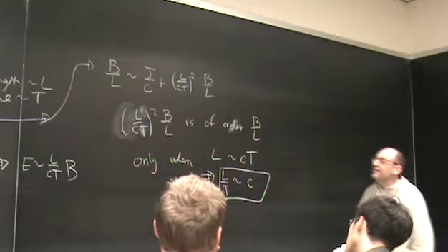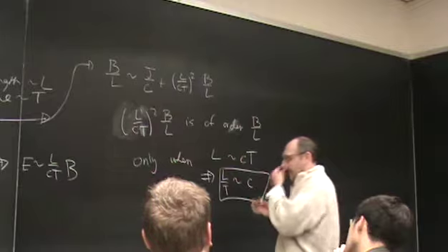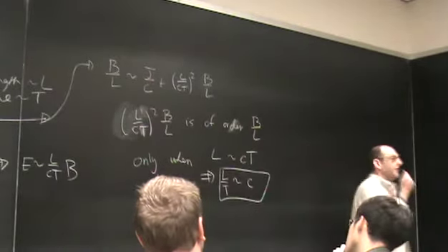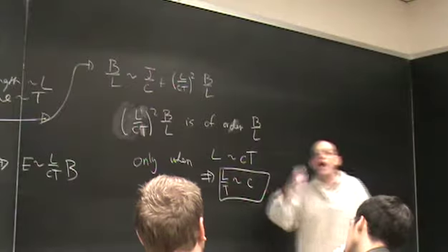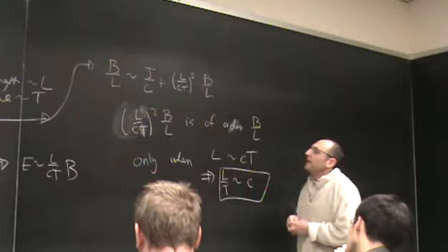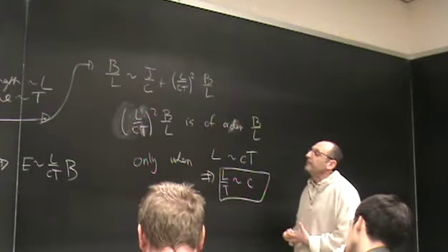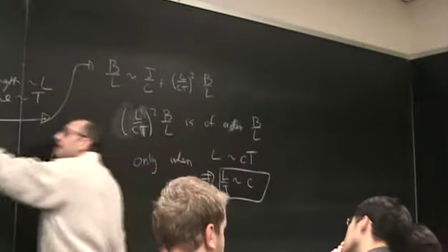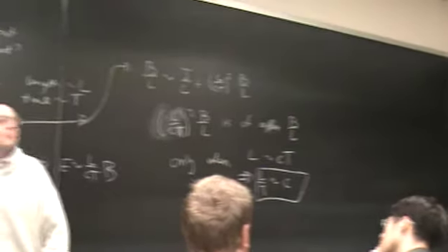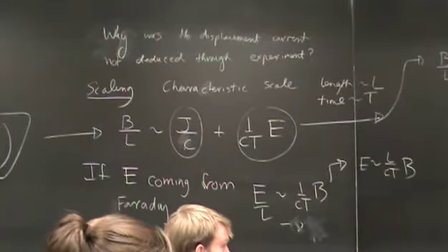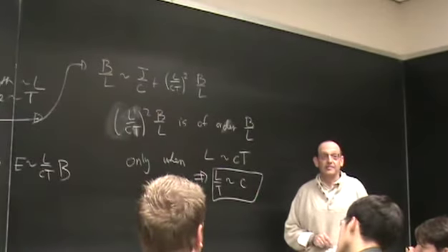So what this says is that if I have a circuit or a charge distribution with changing currents, like RF or microwave, the contribution of the displacement current to the magnetic field in that circuit is going to be tiny unless my charges are moving at relativistic speeds.